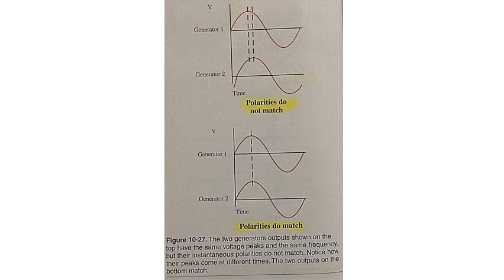A simple way to tell if two three-phase generator outputs match is called the two dark, one light method. Two lights are connected across the phase A and B outputs of both generators in such a way that they match in polarity, voltage, and frequency. Both lamps should not light, since there would be no difference in potential across the lamps.